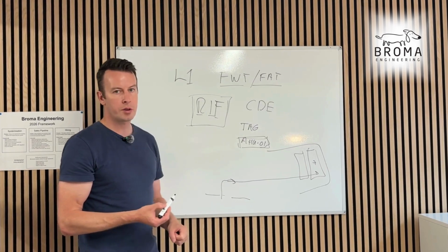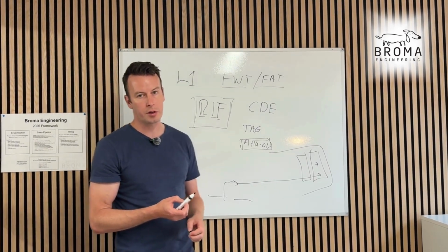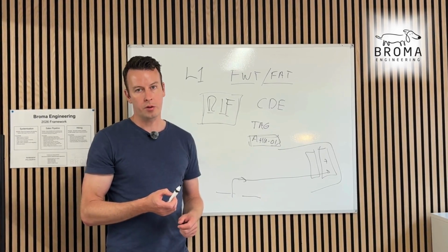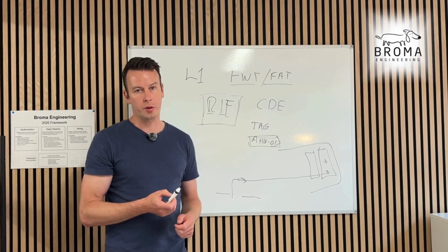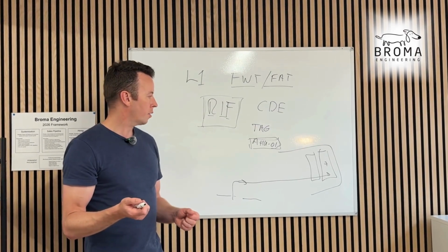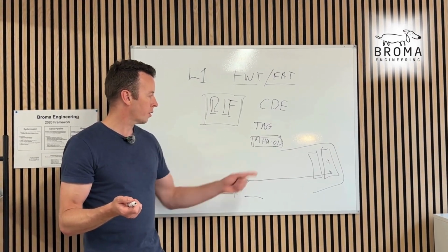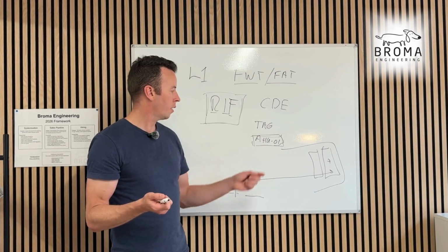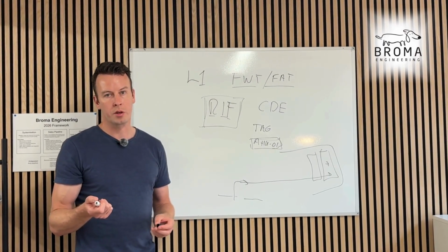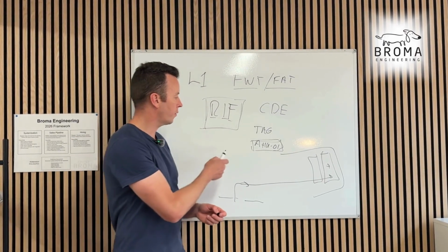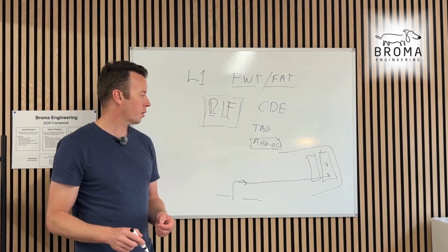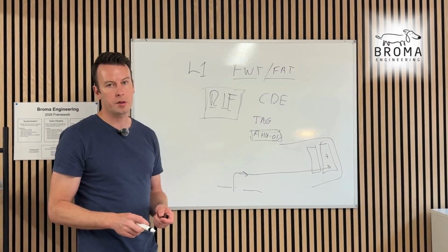So check the nameplates. Always get the manufacturer to write the tag number on the outside of the wrapping, so you know which one is which before you unwrap it. There's nothing worse than being in the middle of winter in a mucky yard, unwrapping, trying to find a tag on the machine when it's pouring rain or snowing. So make sure that you tell the vendor to have this in big writing on the outside in a few places, what tag it is inside.